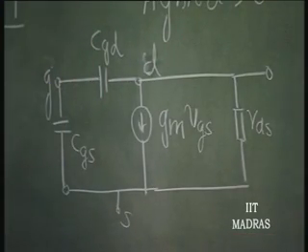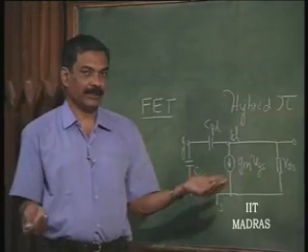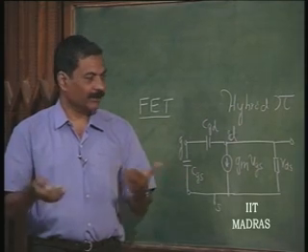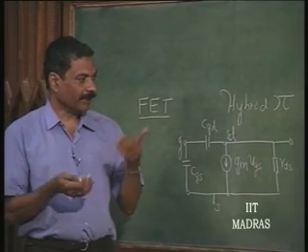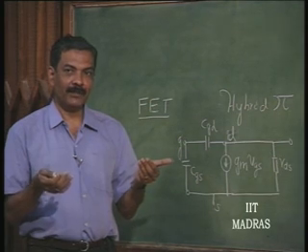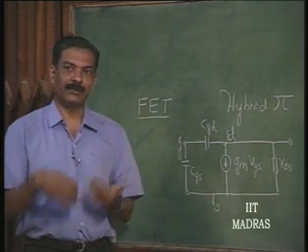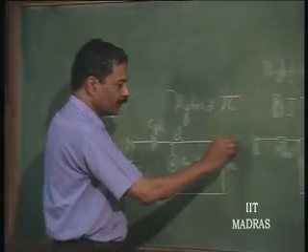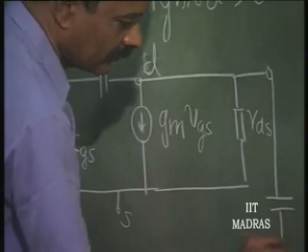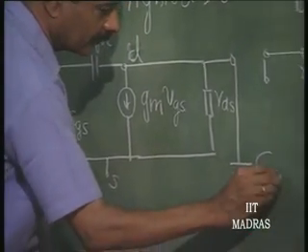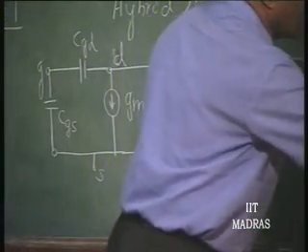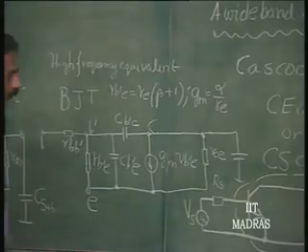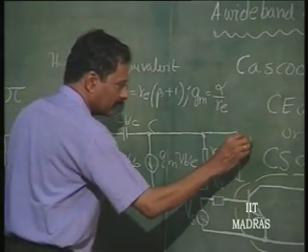If they are integrated circuit components, then these components lie inside what is called a well. A substrate has large number of wells where these devices are put, and each of these wells is separated from the substrate by a junction which is reverse biased all the time. So, that is how you separate one device from the other, and therefore, there is what is called substrate capacitance in each of these cases from this collector well, okay, or this well we have a substrate capacitance.